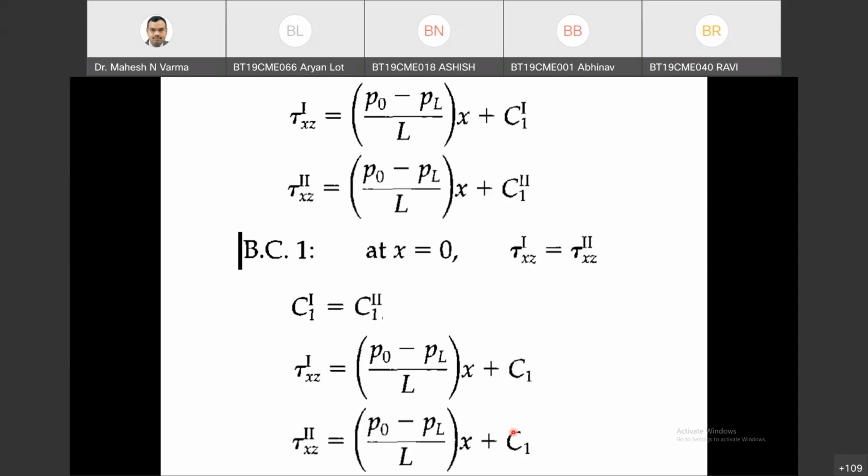So introduce Newton's law of viscosity and get the differential equation for velocity, and integrate that equation and get the profile equation for velocity, which will have three constants, and I have three velocity boundary conditions. Now introduce here for phase 1 Newton's law of viscosity with mu1, relating to the gradient of velocity, and for phase 2 write Newton's law of viscosity where mu2 is relating to the gradient of velocity for phase 2. Substitute Newton's law of viscosity and integrate the equation.